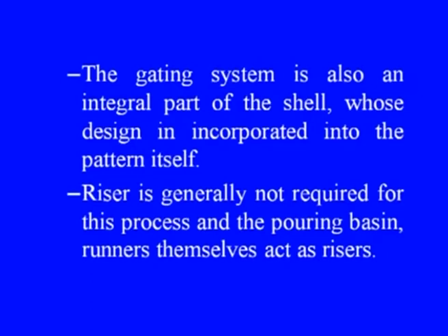The gating system is also an integral part of the shell, whose design is incorporated into the pattern itself. The riser is generally not required for this process, and the pouring basin and runners themselves act as risers.